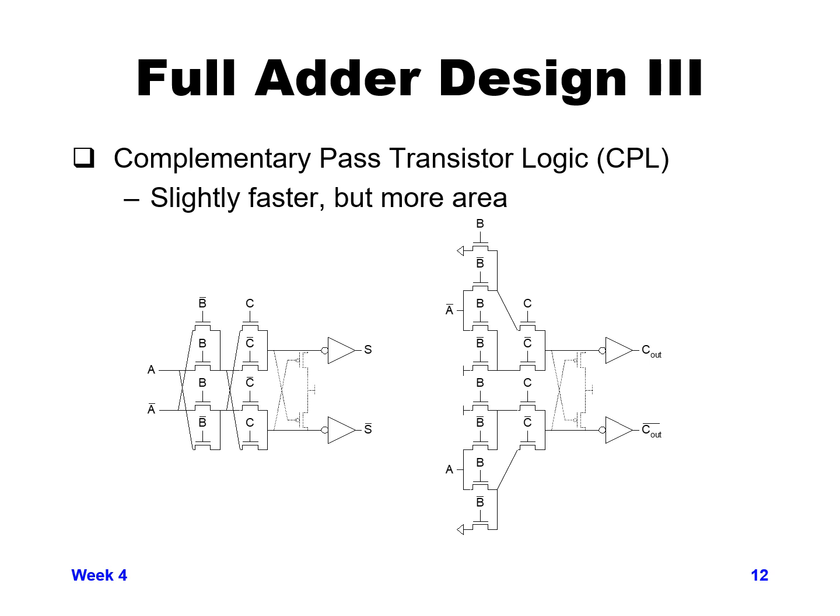The reason for that is a combination of sizing of the transistors plus the way the connections work, there's a lot of cross connections, and you have A, B, and C plus A bar, B bar, C bar. The routing plus the transistor sizing combination just causes a larger amount of area required to get your sum out and your carry out. So depending on what you're trying to trade off, if you're okay with more area but faster, then this could be a good trade-off for you.